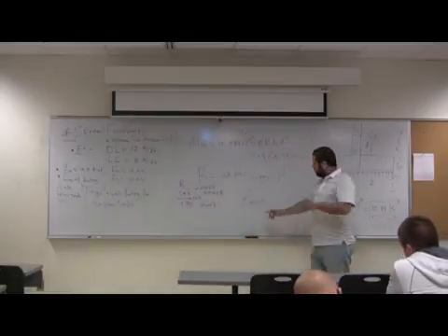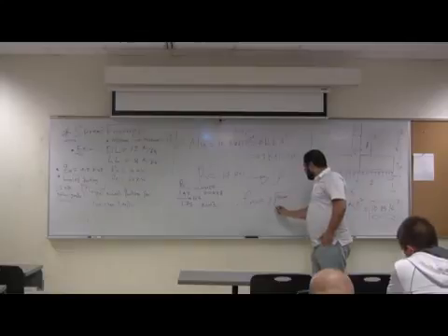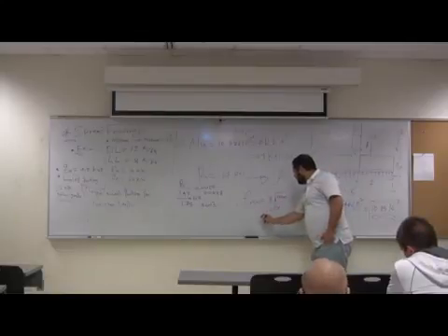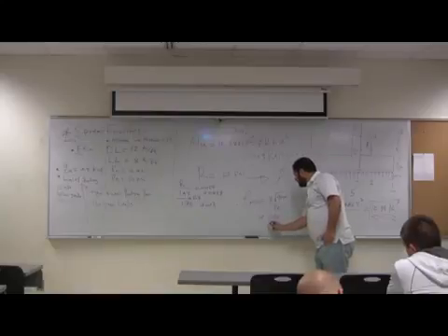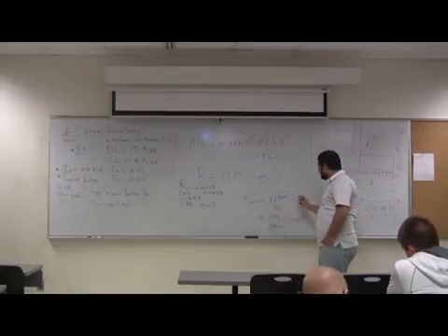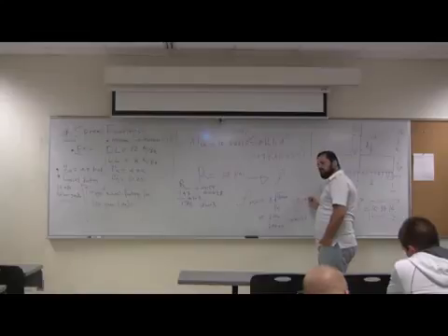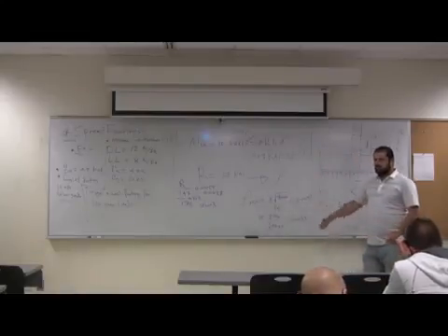Rho minimum equal 3 square root of 4,000 over Fy, or 200 over Fy, which is 60,000. So this gives you 0.0033, and this gives you 0.0034 or 0.0032. You know them.